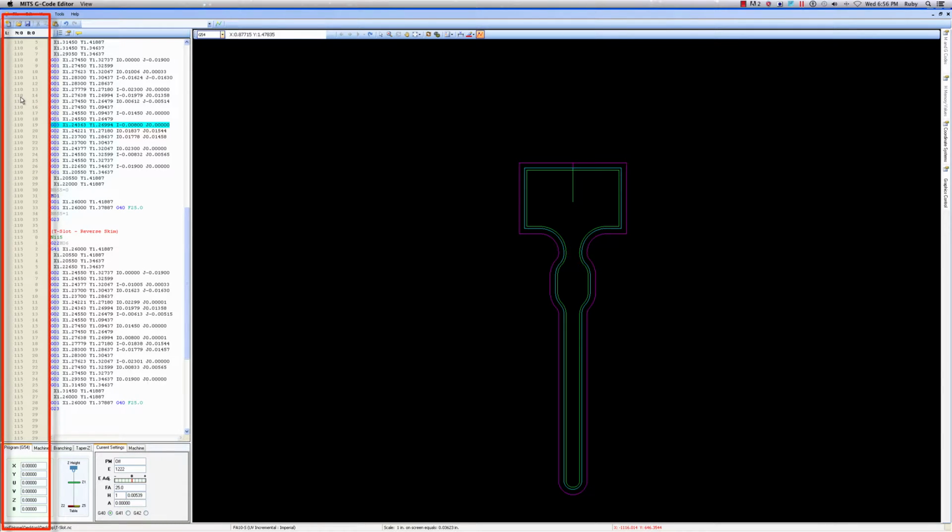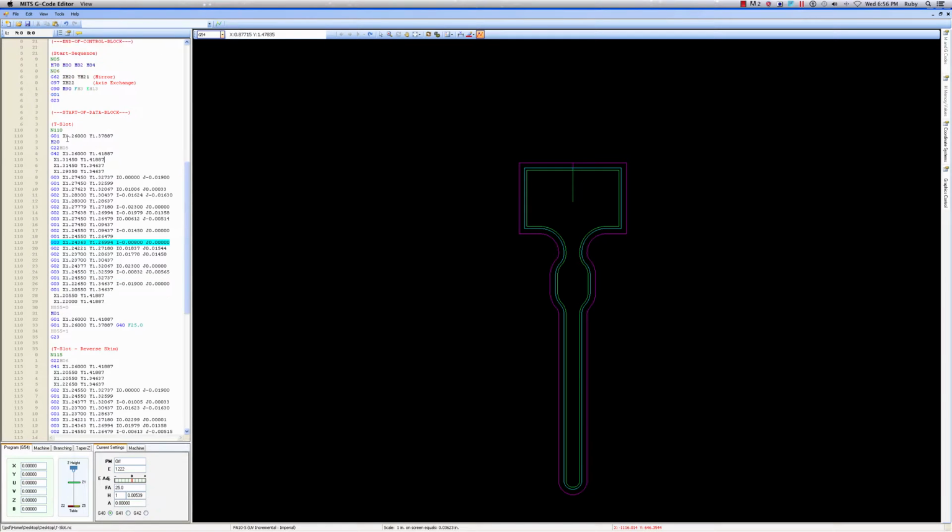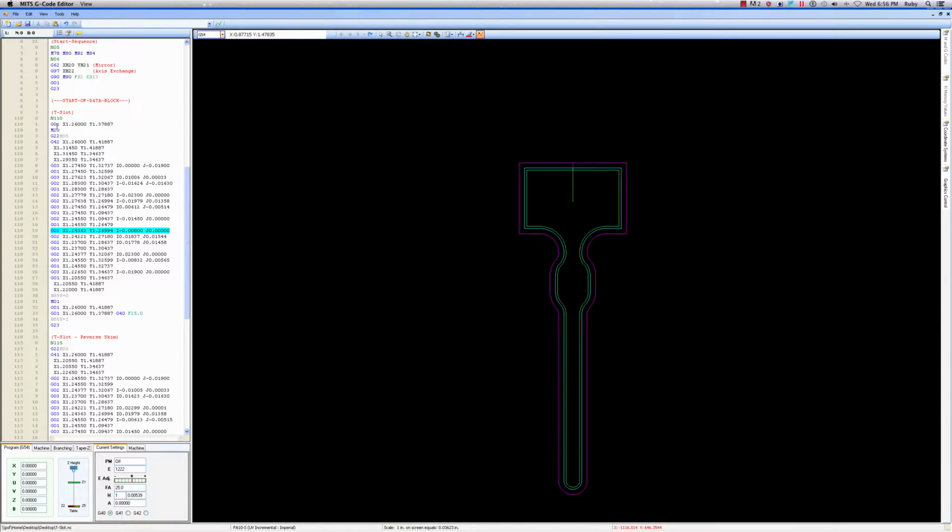On the left is the Mitsubishi numbering system, consisting of the L number, which is the program number, and N number, which is the sequence or subroutine number, and the B number, which is the block number. This numbering system helps you better utilize the power and capabilities of the Mitsubishi EDM wire machine, allowing you to build extremely complex files, which is very difficult or even impossible when you use an N number on each line. The numbering system window can be closed with this icon.